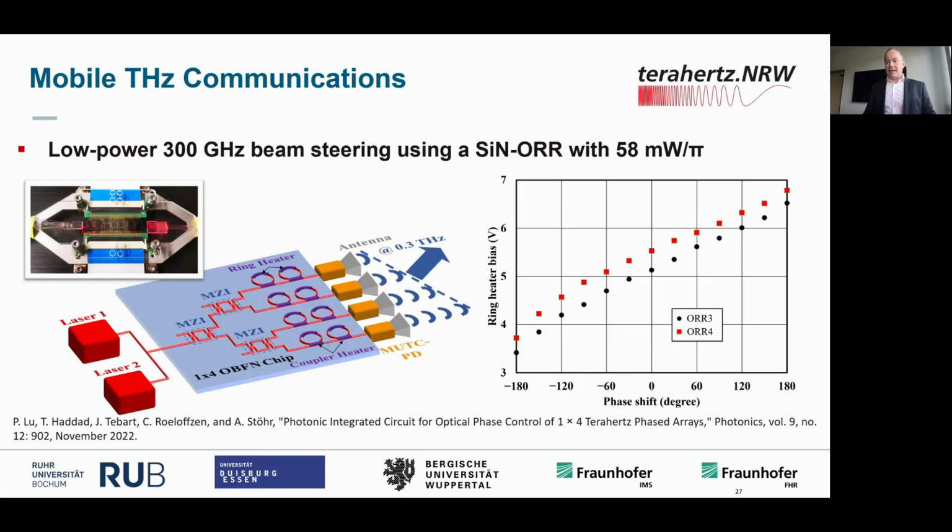And as maybe I didn't mention, but maybe you have seen from the video, the antennas that we are using are highly directive. So in difference to mobile communications, we are using directive beams. And if one of the antennas, or even both, are mobile, we have to steer the beam. And that is done by optical technologies. We have developed different photonic integrated ICs to support this beam steering. This shows you one of the chips, which is using a silicon nitride technology in this case.